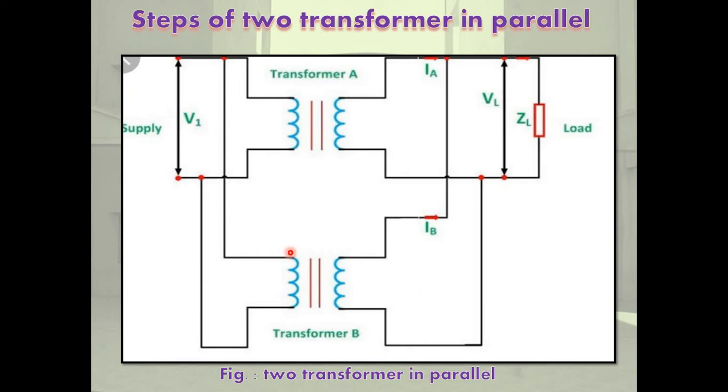So these are the basic important points. First, studying the nameplate of each transformer is very important. Second, confirm whether the transformer polarity, voltage ratio, vector diagram, vector group, terminal markings, kVA ratings, and percentage impedance of both transformers are acceptable for parallel operation. If not, do not connect, because these are the parallel operation conditions.